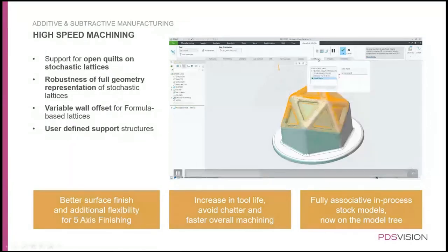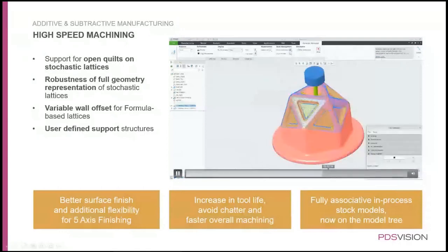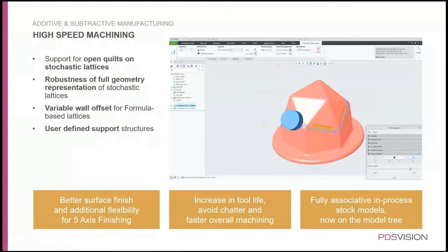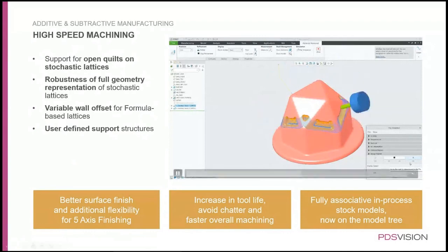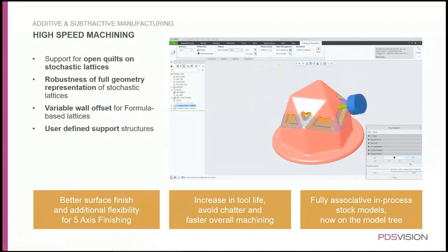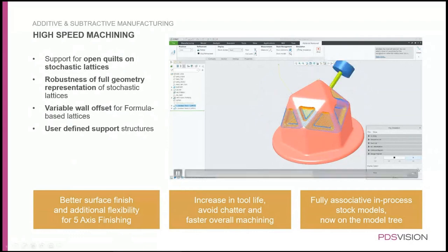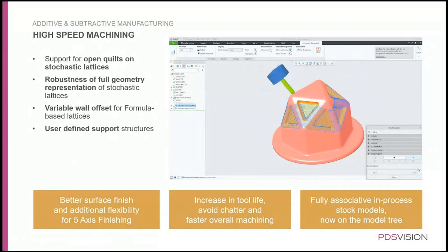Shall we jump a bit forward with the slides? And as you can see, well, not that much maybe. We will go around the piece, gradually driving ourselves to that cuttable metal, and of course it depends on your work-in-progress model how much you will cut at each slice. With some softer materials you can really do it like this. With harder ones you can't. But as you can see, the milling head is not really jumping back and forth. It tries to give you a pretty constant angle while it's circling to the top of the piece.